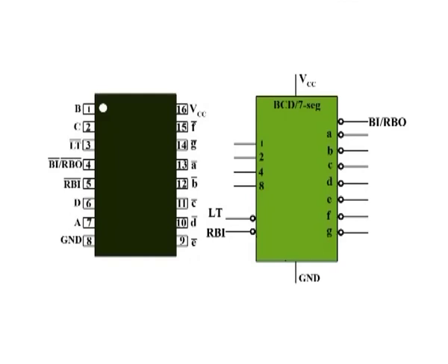The BI function is not part of the zero suppression capability of the device. All of the segment outputs of the decoder are non-active or high if a zero code is on its BCD input and if its RBI is low. This causes the display to be blank and produces a low RBO.